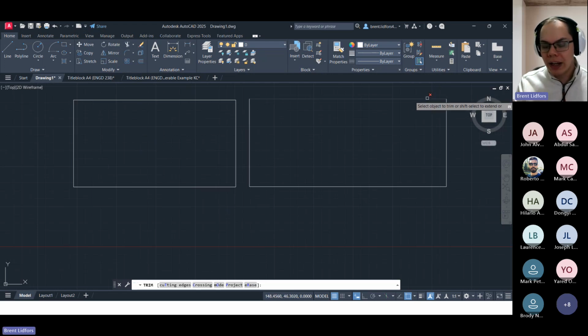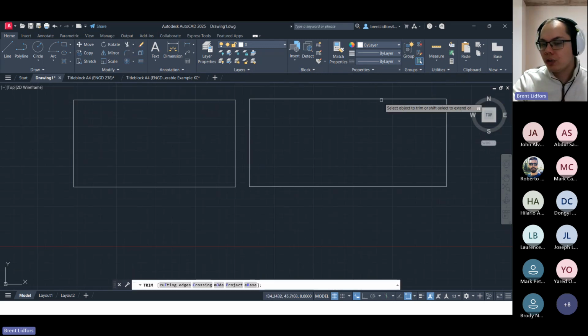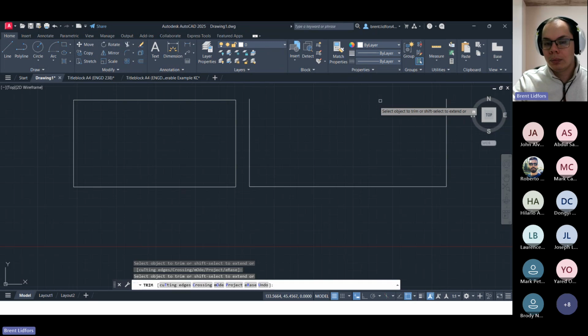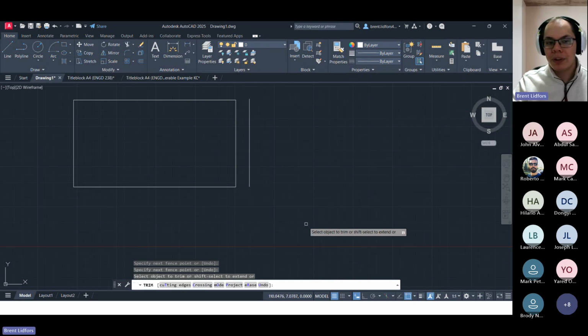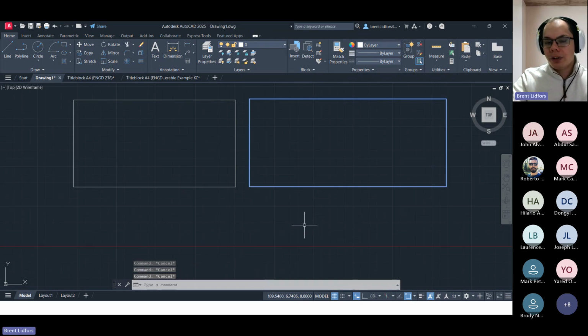And then it's removing the line segment between those two coordinates. And this works for any intersection. So if I choose something like this line here, there's an intersection between this line segment and the one on the left, and there's an intersection between this top line and the one on the right. So it's going to remove the line segment between those two lines. Okay, and I can drag through multiple, cut multiple away at the same time. And this works for all intersections.